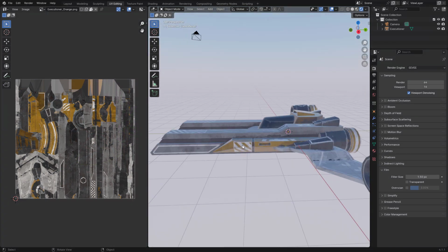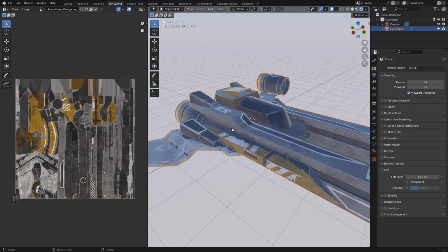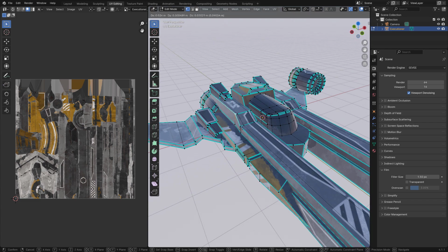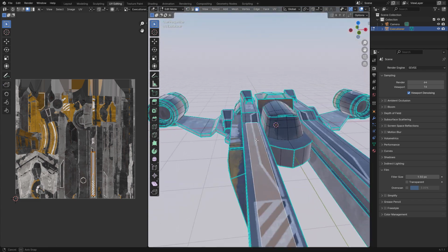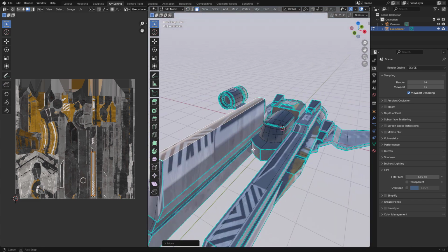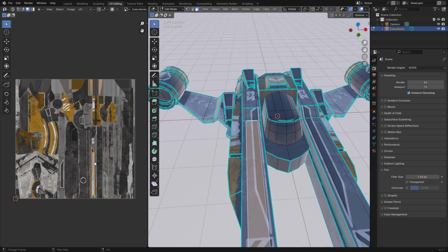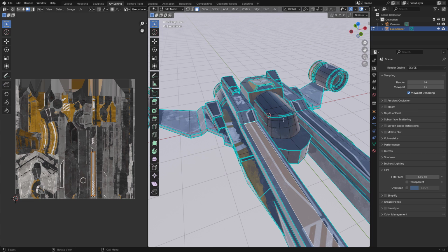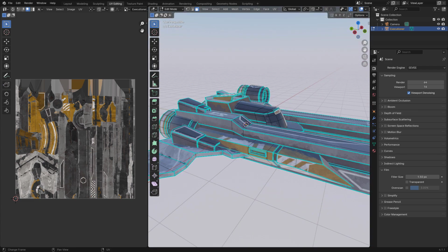First of all, the concept of UVs needs to be clear. The coordinates of the UVs are linked to the vertices of the mesh. If I move the vertices, the coordinates move with them. Only when I directly manipulate the UVs, for example, in Blender's UV editor, do they change their position in relation to the mesh.